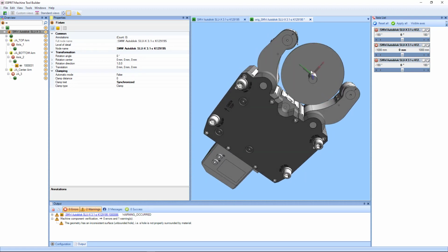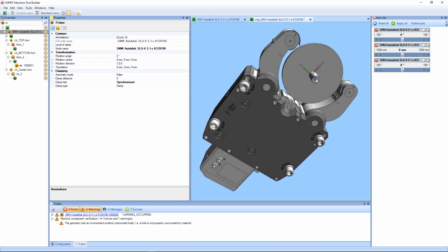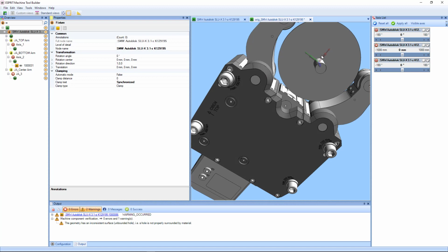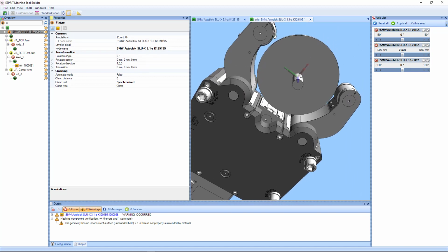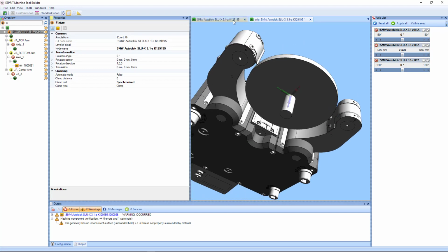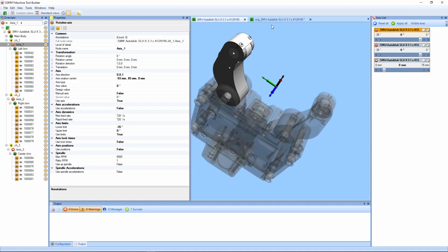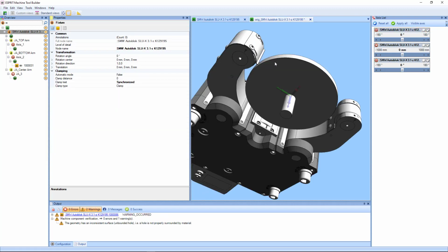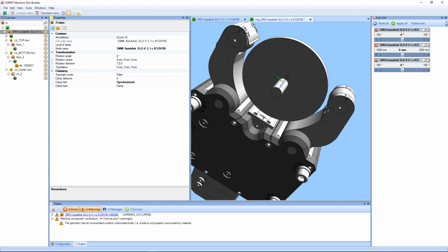So you can position these a little bit beyond if you wanted to, if you want to calculate that angle, or if the specifications of the steady rest tell you what that is, that's great. I used 0 and 35 degrees for mine. And you'll notice as well, just really quick, this original, I deleted that cover, because the way that it was modeled inside the original, this should be rotated back if you wanted to, where these set screws or holding screws are, but it was interfering with the bar stock.